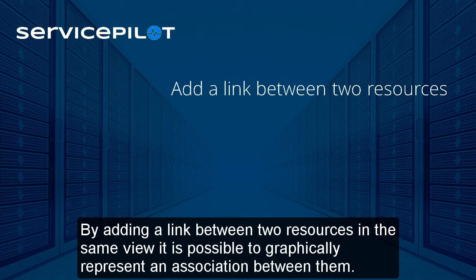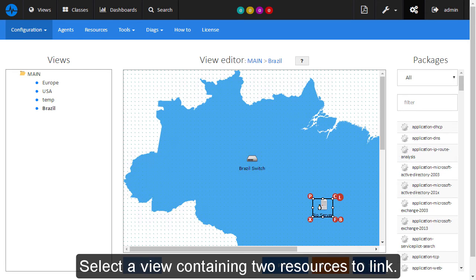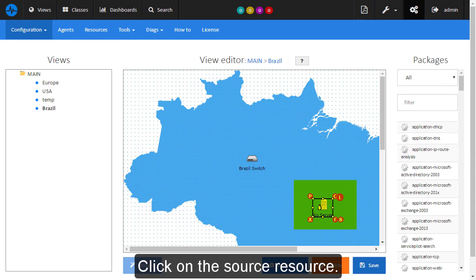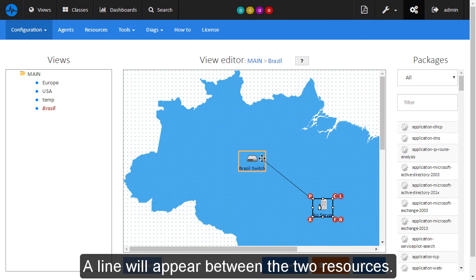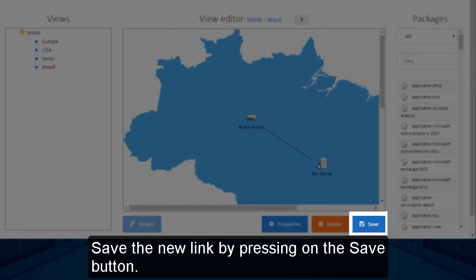By adding a link between two resources in the same view, it is possible to graphically represent an association between them. Select a view containing two resources to link. Click on the source resource. Click and drag from the L button on the source resource, letting go once over the second highlighted resource you wish to join. A line will appear between the two resources. Save the new link by pressing on the Save button.